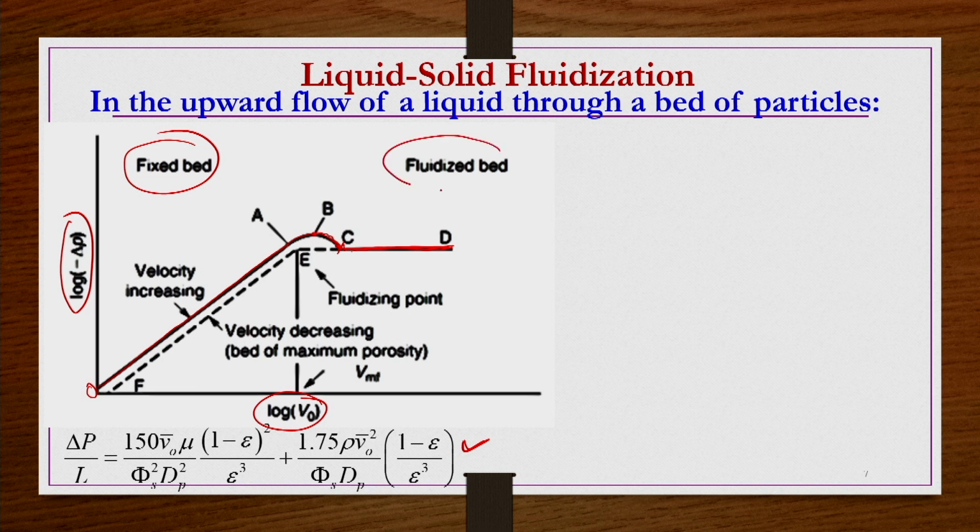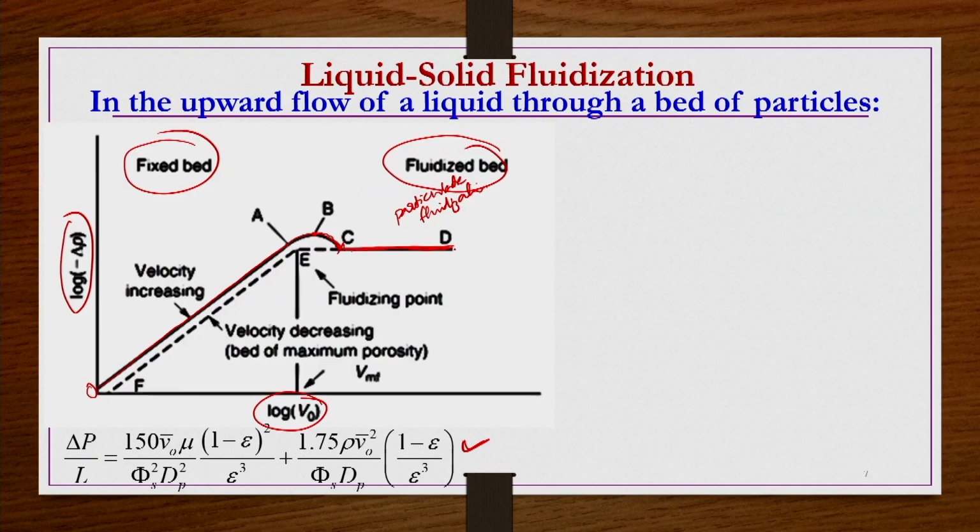So, this is a kind of fluidized condition, and we are talking especially about liquid-solid fluidization. So, we can say it is a kind of particulate fluidization, where the bed uniformly expands, and the bed density is going to be the same at different locations within the column, wherever you take it within the expanded bed. So, the pressure is going to be the same.